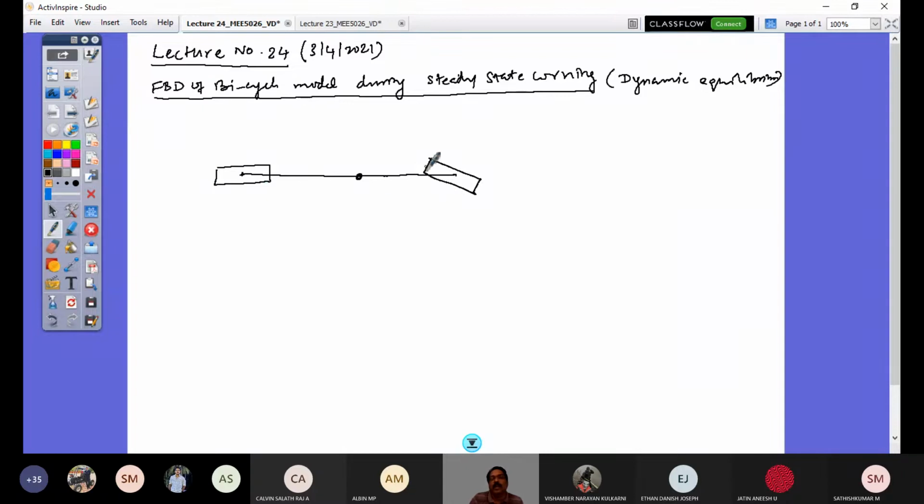This is the front axle or front wheel plane, and if I extend this line, this is our steering angle, the steering input. Because of the steering input, you see that there is slip developed. So this slip angle is alpha f. That's measured in this direction. That's why we always take minus alpha f. Same way at the rear axle, we get alpha r.